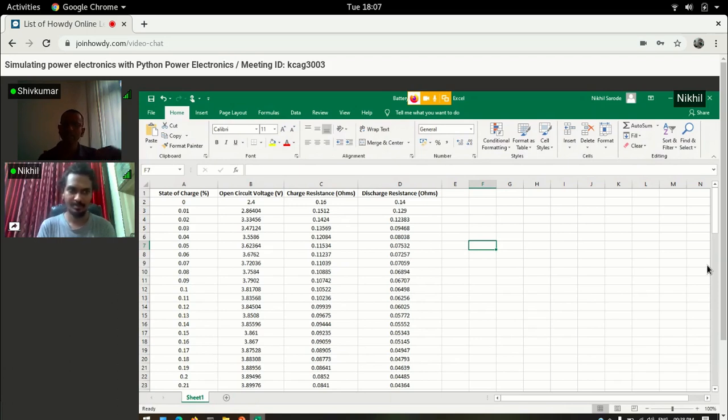Now the next part is, we need the capacitance, right? So how do you calculate the capacitance? Is that a parameter, or do you plan? No, it's not a capacitance. It is the capacity of the cell. For example, 2.6 ampere hours or 2.3 ampere hours, whatever it may be. It is a typical value of a lithium-ion cell. So it can be given as a constant? You mean the value of C that you have shown in that equation? Yes. Capacity of the cell, we can assume constant for normal operations.